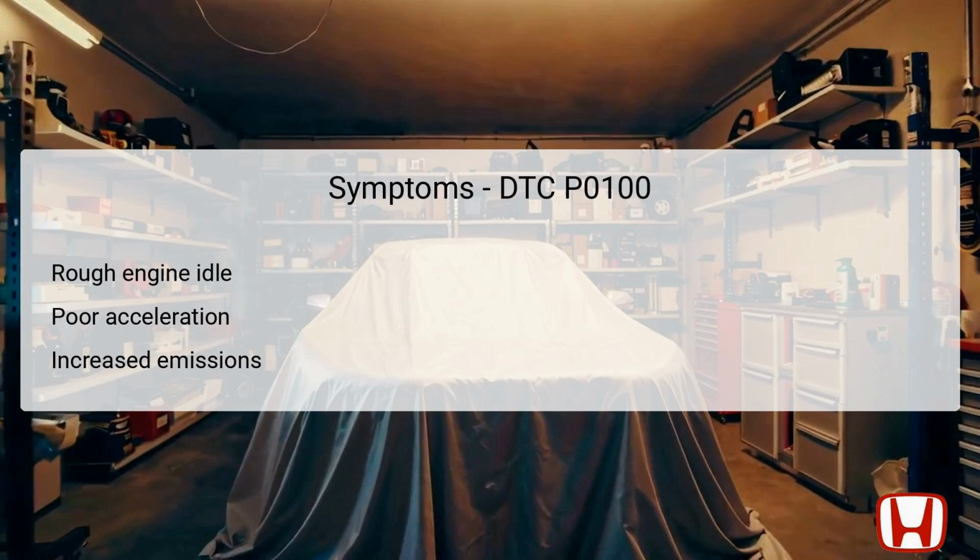When DTC P0100 is present, you may notice several symptoms affecting your vehicle's performance. One of the most common symptoms is a rough engine idle, which can lead to an uncomfortable driving experience. Drivers may also observe poor acceleration as the engine struggles to receive the correct air-fuel mixture for optimal performance.